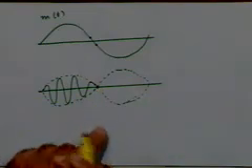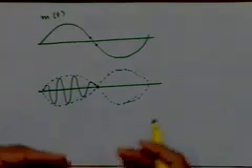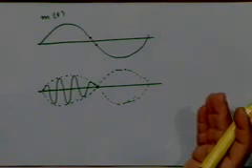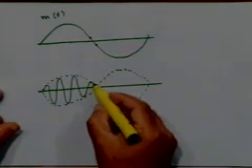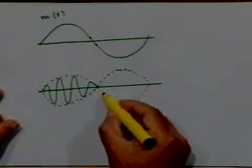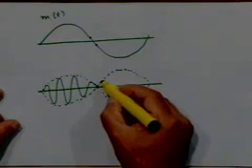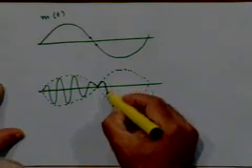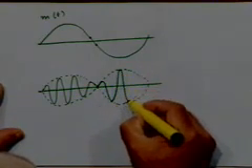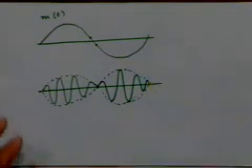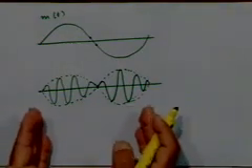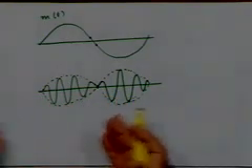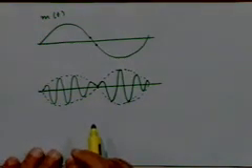The phase of the carrier will suddenly go through a phase shift of 180 degrees. Is that clear? So the carrier will not continue smoothly, keep on going like this. There will be a certain phase variation by an amount of 180 degrees. So you will start once again like this, and so on and so forth, right? Of course, my picture is not perfect. The carrier cycles are not of uniform duration, but they should be, because the carrier frequency remains the same throughout.